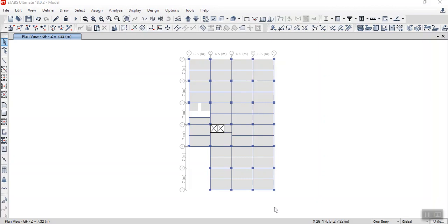Today we are going to design reinforced concrete slab in CSI SAFE. This video includes the process to export slab data to a SAFE file from ETABS and import the slab data to CSI SAFE. Also, we will learn how to define load combination, materials, slab sections, and check short-term deflection as well as long-term deflection of slab in the software itself. At last, we will design the slab as per Indian Standard Code.